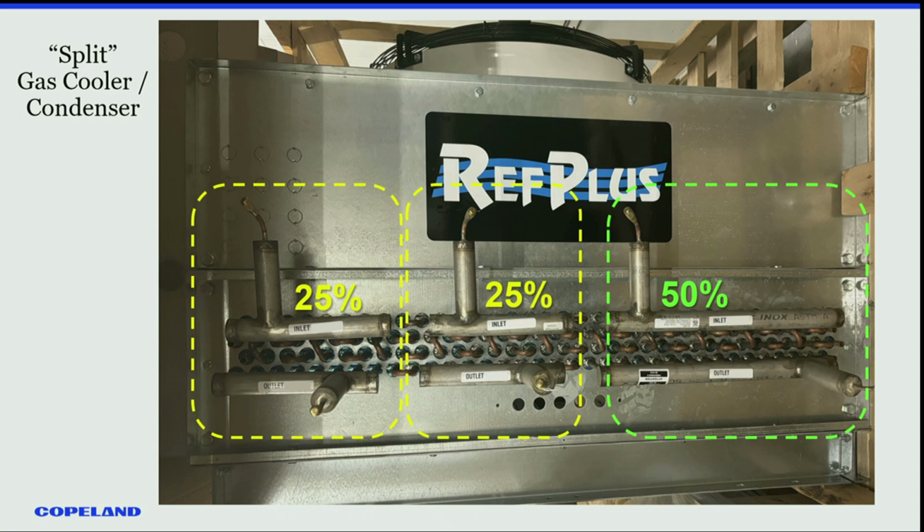On the study that I showed you, we looked at 100 different CO2 stores across the US. It was apparent that a lot of the cold ambient areas would have benefited from split condensing. Instead of having the gas cooler fans trying to manage it, you're down at 15%. You still want a bit of airflow on there, but it's so much airflow that now the high pressure valve's got to start backing pressure up instead of just letting the gas cooler manage it. So different conversations are happening around. We'll see where it goes.